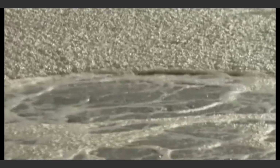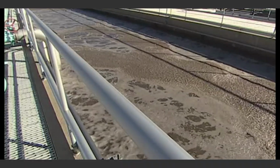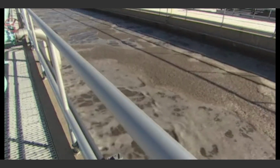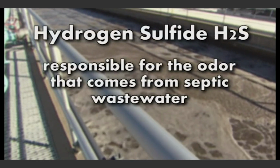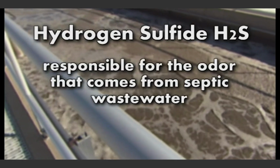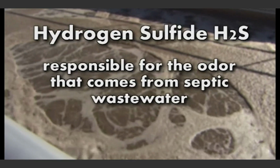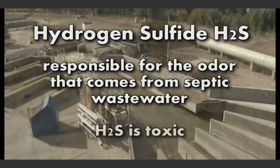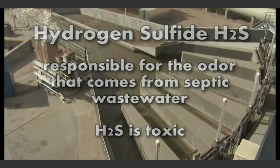Pre-aeration also helps to separate grease and oil from the wastewater and wastewater solids and to carry them to the surface. Pre-chlorination can achieve similar results. Hydrogen sulfide is responsible for the rotten egg odor that comes from septic, anaerobic wastewater. Sulfates in wastewater break down into H2S, which is heavier than air and will collect in manholes, pits, etc., posing a safety hazard and odor problems. H2S is toxic, and all safety precautions are essential.